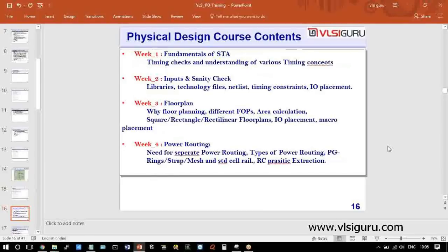Libraries are very important. TSMC, UMC, GF will be giving you libraries. All these cells finally have to go to TSMC to get manufactured. They will create the library. There will be SPICE models, which are transistor models. They will do characterization with the SPICE model and come up with tables, like NLDM and CCS: non-linear delay model and composite current source models.